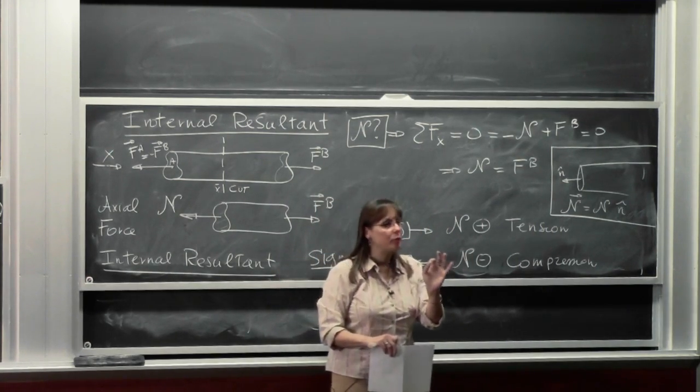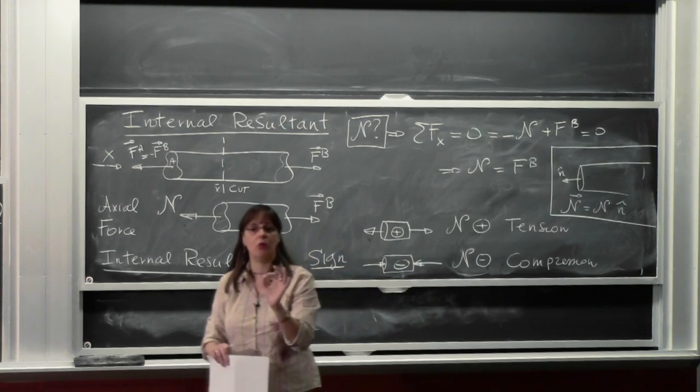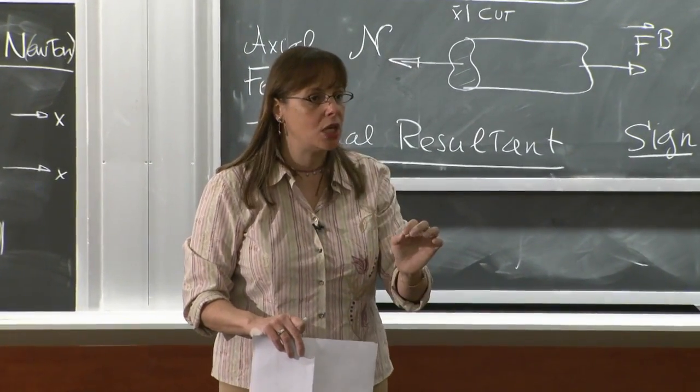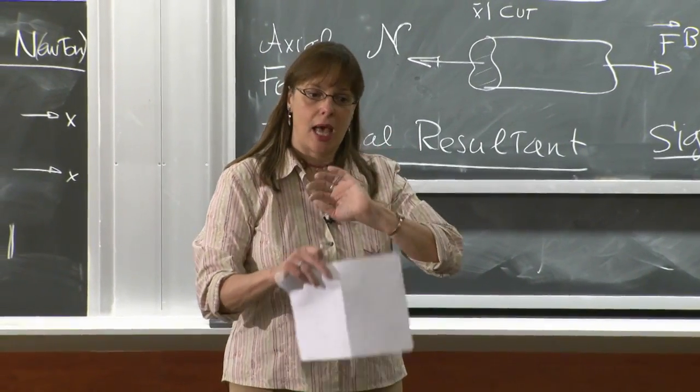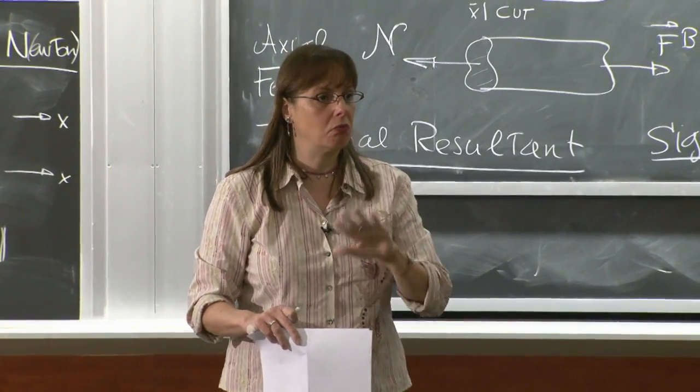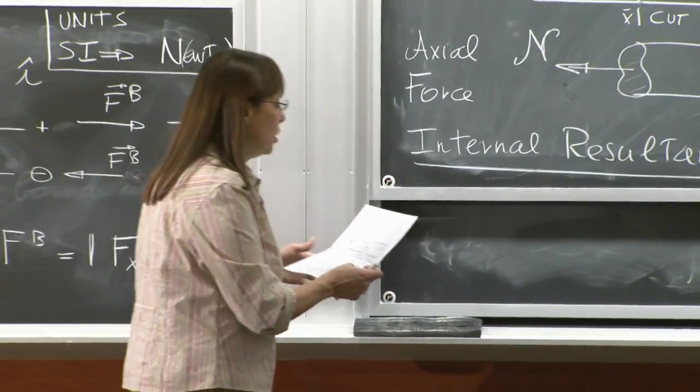But for practical purposes for this class, all I want you to understand is that when you make a free body diagram, expose an internal force, and you see that you have to calculate the internal force, you put your n coming out of your cut section. That's it. And things are going to be good. Okay.